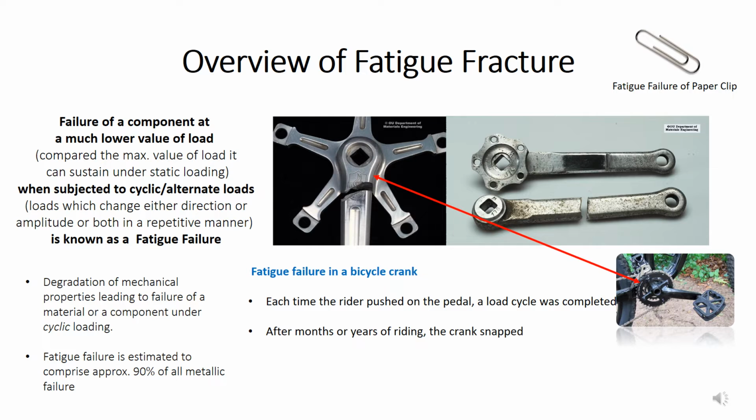If we want to break this paper clip into two parts, firstly we will straighten the wire. After straightening, if we apply tensile loading on both ends of the paper clip, or you pull the wire from both ends, you will observe that it is very difficult to break. But if you hold one end of the paper clip firmly in one hand, and on the other end you move it in to and fro directions, you will observe that it is very easy to break this paper clip.